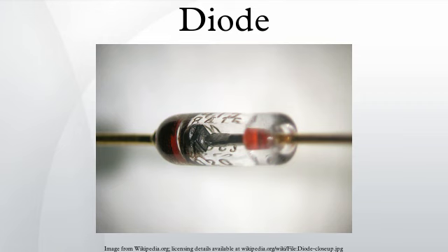PIN diodes. A PIN diode has a central undoped, or intrinsic, layer, forming a p-type/intrinsic/n-type structure. They are used as radio frequency switches and attenuators. They are also used as large-volume, ionizing radiation detectors and as photodetectors. PIN diodes are also used in power electronics, as their central layer can withstand high voltages. Furthermore, the PIN structure can be found in many power semiconductor devices, such as IGBTs, power MOSFETs, and thyristors.